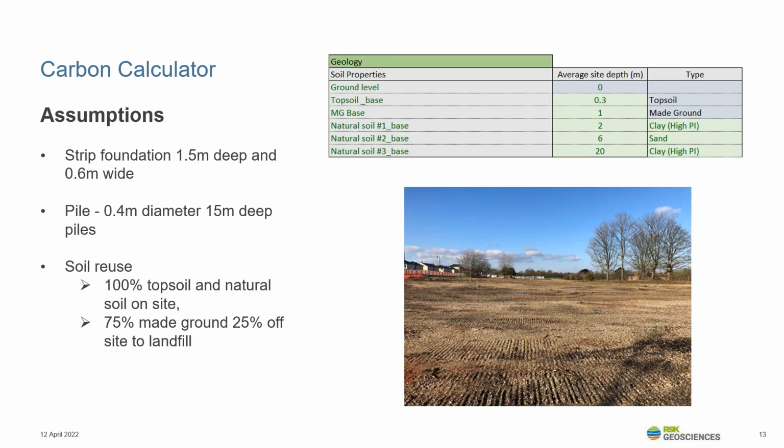We've made the assumptions for the waste stream and soil reuse as per our recommendations and our remediation method statement. So on this site, we've assumed full reuse of the topsoil, reuse of 75% of the made ground, and 25% disposed of off-site to landfill, and the reuse of all natural soils on site as part of their cut and fill exercise.